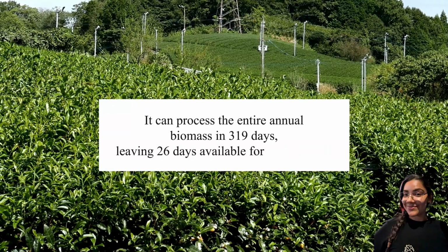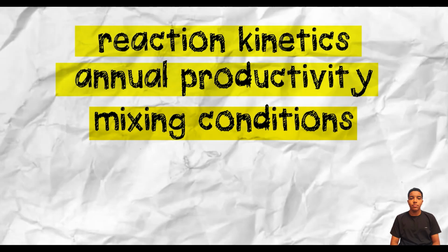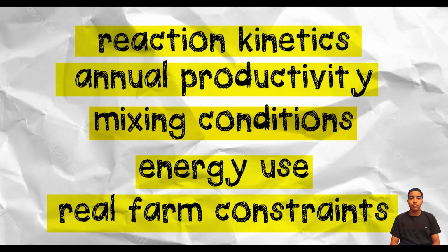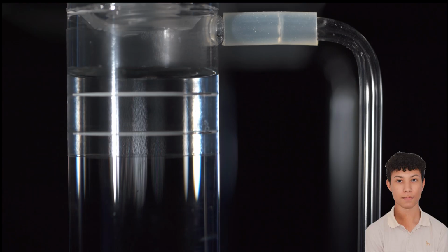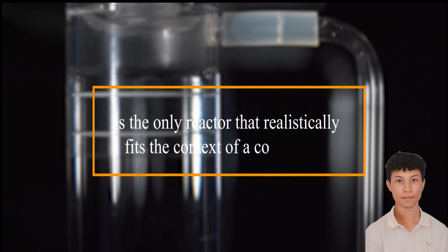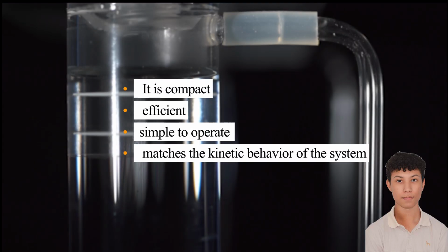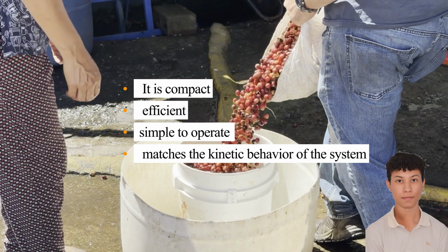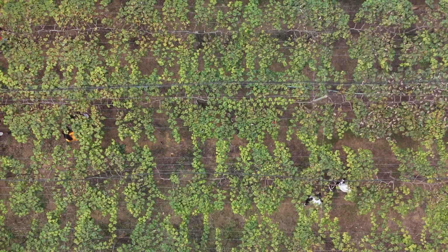Selection. When we consider reaction kinetics, annual productivity, mixing conditions, energy use, and real farm constraints, the conclusion becomes clear. The CSTR is not only the best option, it is the only reactor that realistically fits the context of a coffee farm. It is compact, efficient, simple to operate, and matches the kinetic behavior of the system.